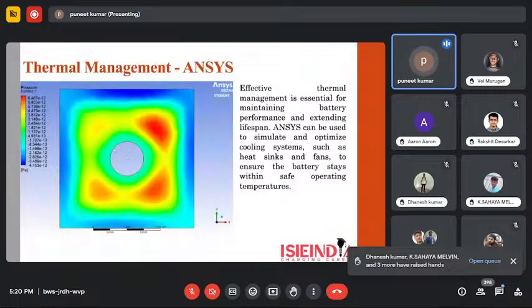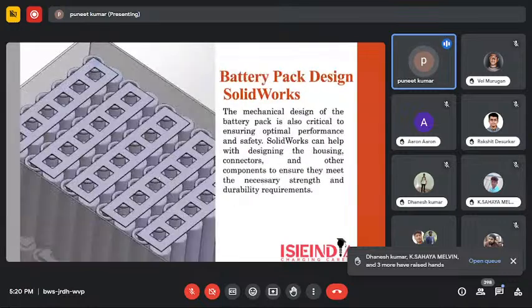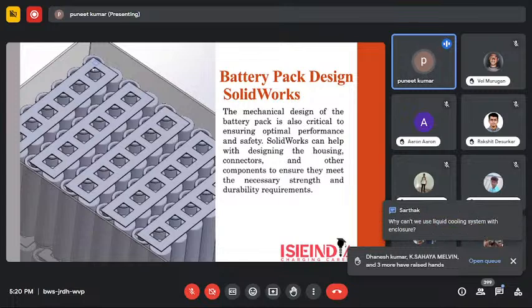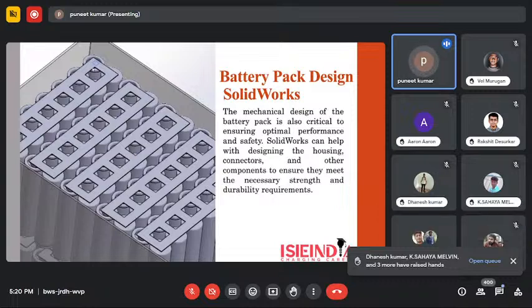Once heat starts moving, it will move out to a certain length. This is one certain pattern that heat will follow, so you can optimize your design accordingly. You can give either a safe space between these two cells, or you can add some material, like FR4 or something, you can use them as well.